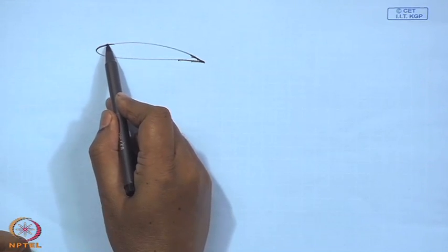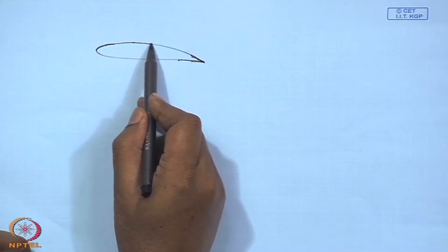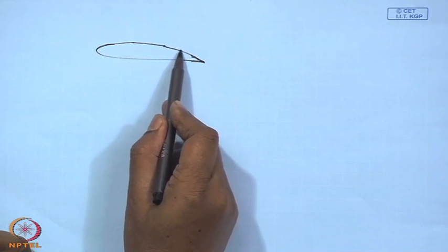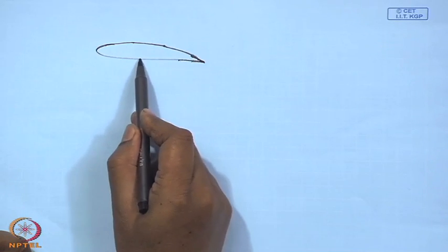Of course, in a viscous flow, it is no slip, that is everywhere the total flow velocity is 0, both the tangential and normal components. But in inviscid flow the flow is tangential to the surface, both on the upper surface and lower surface, meaning that the streamline adjacent to the airfoil surface is parallel to the airfoil surface.